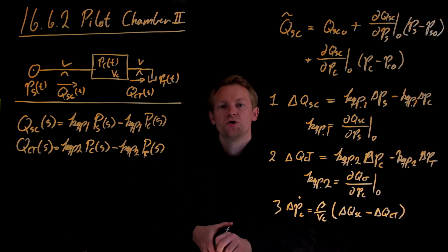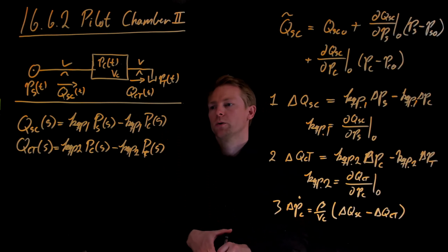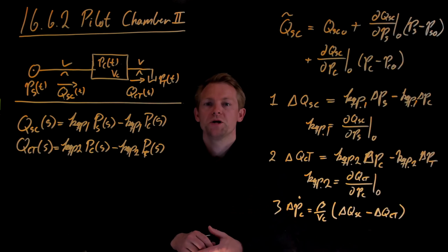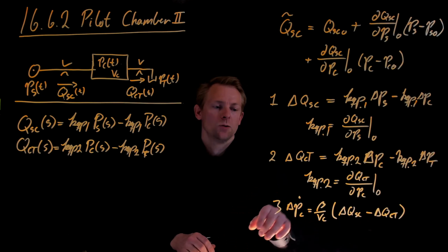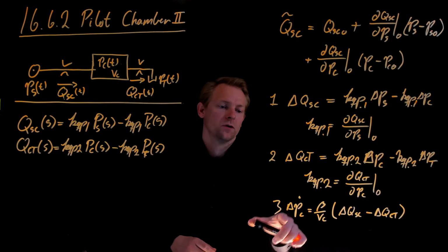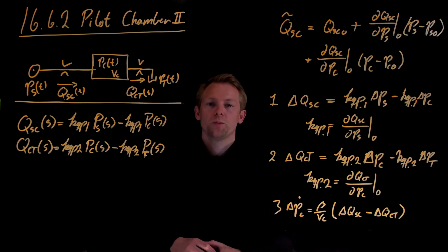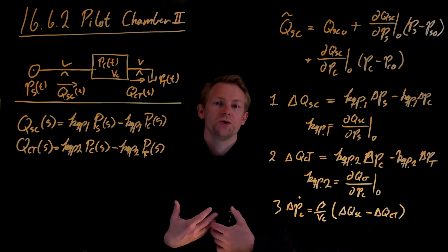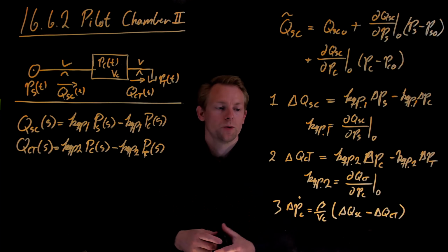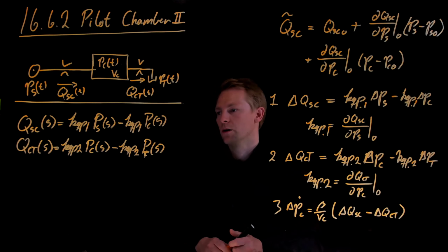So that is the two orifice equations, quite straightforward. Continuity equation, and here we'll have an S coming out of the differential term being Laplace transformed, and we will assume that the initial condition is 0 so that we don't have this extra term that comes on in the Laplace domain.